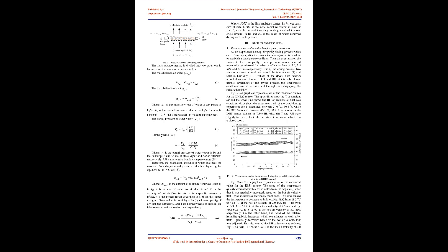The 2 sensors were calibrated. The temperature, T, and relative humidity, RH, of the DHT22 sensor were calibrated by a hot wire air velocity meter, TM4001, in T and RH function, with an accuracy of plus or minus 1% for T and plus or minus 5% for RH. And the EE31 sensor was calibrated by the indoor air quality monitor QTRAK model 7575. Mass balance method.